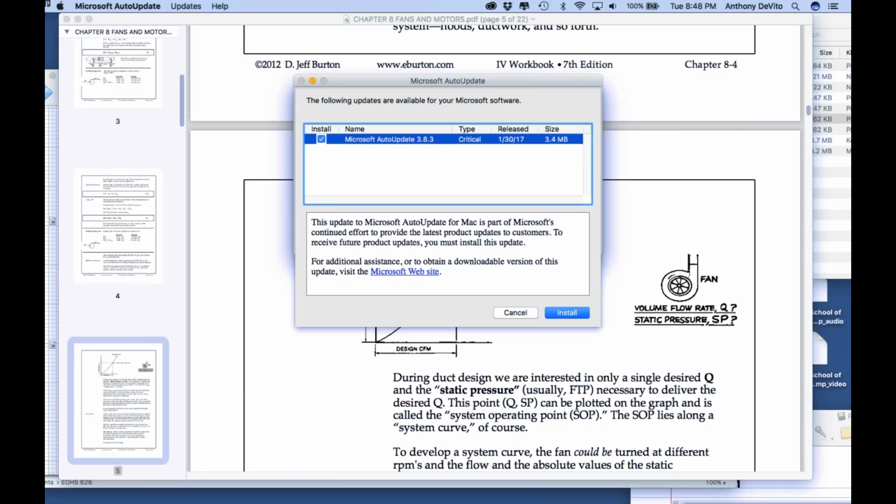If you just look at the velocity pressure, you're just going to see what it takes the fan to move that air, without making up for all the losses in the system. When you connect that ductwork, you haven't taken into account all those losses because you didn't consider the static pressure that you need. So you're not going to move the fan at that speed. You're not going to meet that Q that you think you're designing it for. And this is to be able to move whatever contaminant.